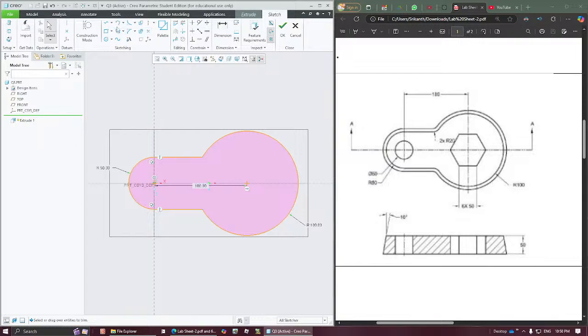So for that we'll have to use the fillets. This option is a fillet. Click the first edge, then the second one here, and the same I have to create here as well. Click the middle mouse button to come out of that, and you can see that we are giving the radius only once. So I just need to make it equal. Click on the equal constraint and select the 2 fillet arcs, which will make the radii equal, so now if you change the radius here, the one at the bottom will automatically change.